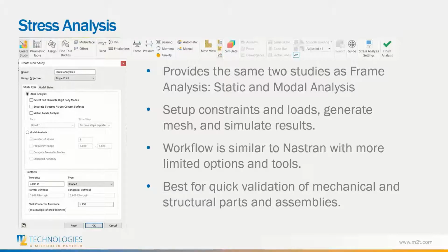Within the stress analysis tool, you're able to set up constraints such as fixed, pin, or frictionless constraints. You're able to apply loads such as a force, a pressure, a bearing load, moments, or even gravity. And then you generate that mesh using automatic mesh generation or refinement tools as needed, and then you can simulate and analyze the results from there.